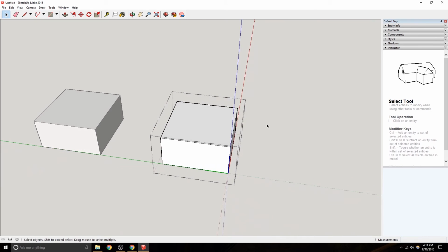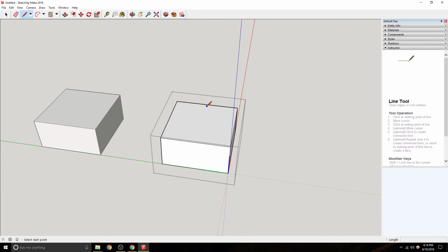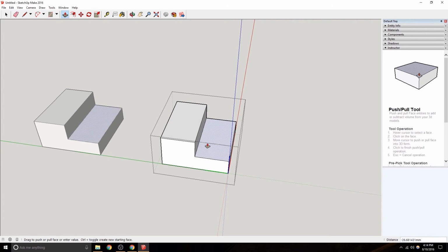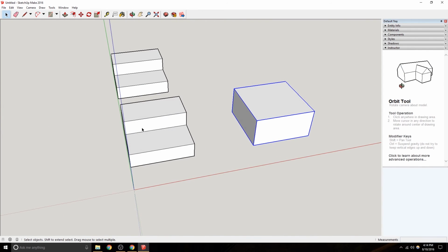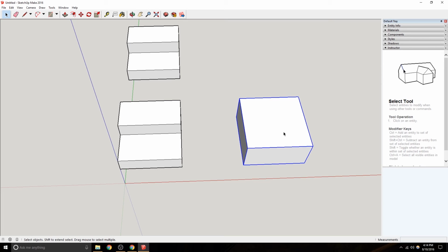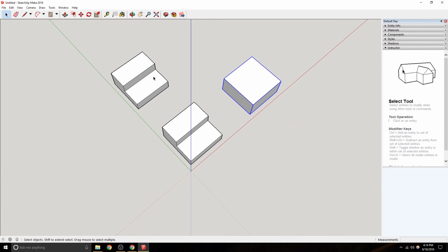It's going to modify the second one. So if we do something like drawing a line and take a chunk out of it to the midpoint, let's say, it's going to modify that one. Now this one was a copy over here, but we did not make it part of the same component. So let's say we take this one and we've modified two of these, but this one's slightly different than this one.